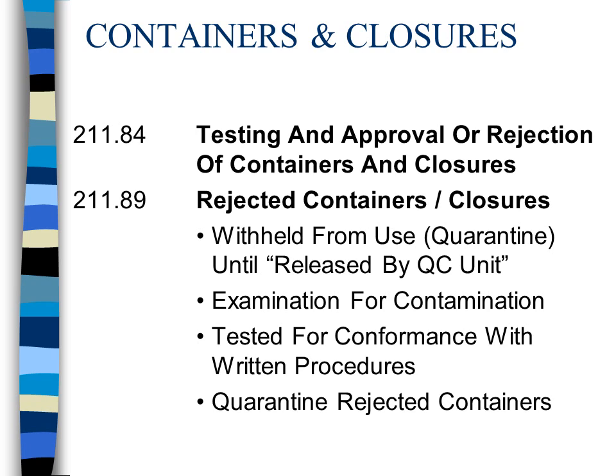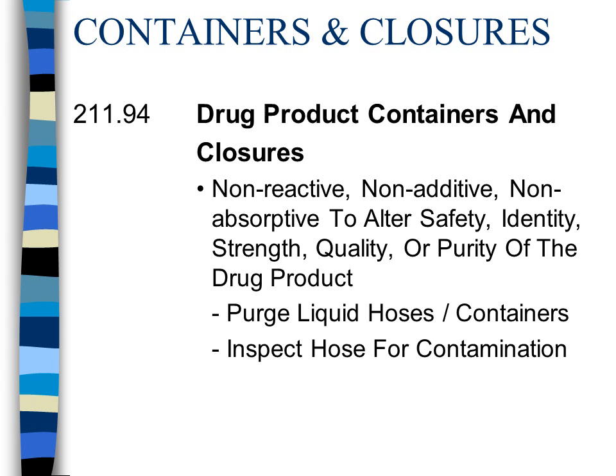If you are at a home care customer location, be it a rest home or a patient's home, and because of the inspection that you did on that container, you deemed you could not safely fill it, leave the DME a note as to why. Also, contact your QCU member so the QCU member can contact the DME and let them replace the unit.